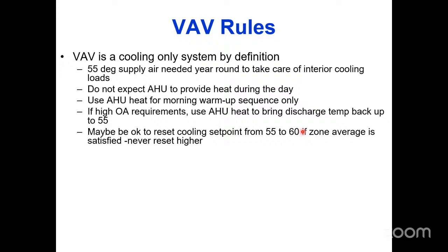Historically, we did that reset with an outside air temperature sensor. And as it got colder outside, we would start resetting the indoor supply air temperature up a little bit higher. In a modern system, once again, we have DDC controls. All the VAV boxes are communicating and talking to the air handler controls. So what we can do is look at all the zones and say, hey, on average, are you guys good? Like you asked me, as a group, to be at a 71.8-degree indoor cooling set point, and as a group, you guys are at like 70.5. Like you got too much cooling. Why don't we cut it back a little bit here? I'm going to provide you 58-degree air for a while and let's see how it goes. And you can do that.